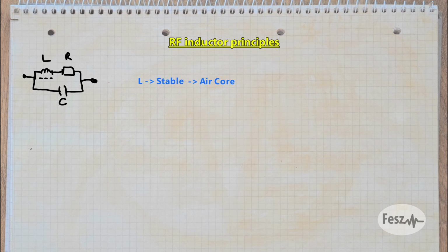The common response shape is a flat line, which at some point shoots up and then down. This transition occurs at the self-resonant frequency. After this point, the inductor starts to behave like a capacitor. The exact frequency at which this resonance occurs is calculated using the parallel capacitance, and well, the stable inductance is maintained up to about a decade below the resonance frequency.